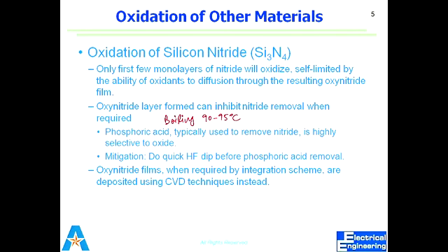So can we, in general, think of oxynitride as an oxide in most of its properties? Oxynitride is actually when you have silicon nitride and then you put that wafer that has the silicon and on top has silicon nitride, you put it at high temperature in an oxidizing ambient.